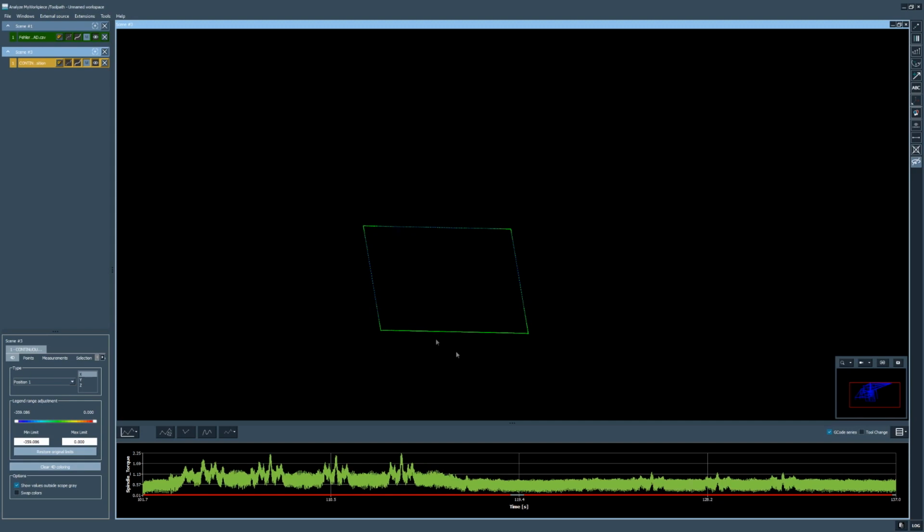So this would be now here, and now we see, okay, that the spindle torque goes from 0 to roughly 1.7. So we now also could use a color coding and say, okay, limit it to 0 and 1.8, or let's say 1.7.